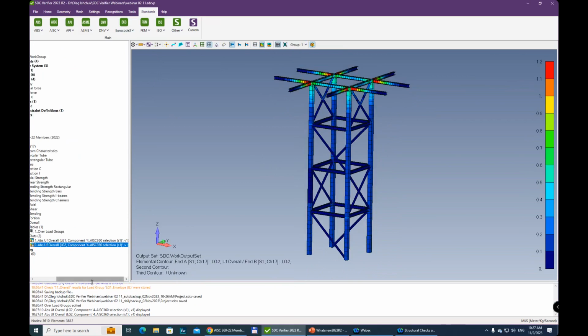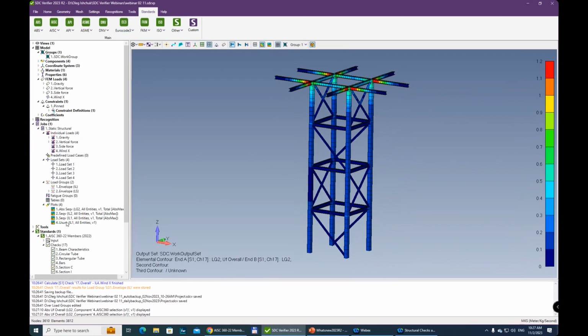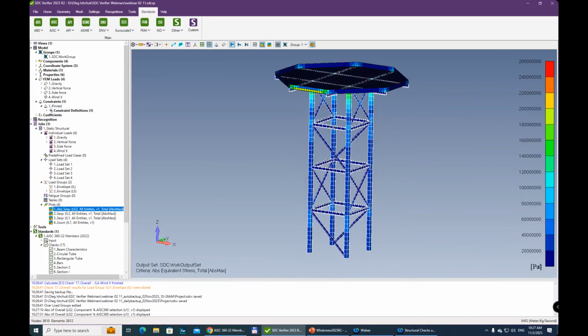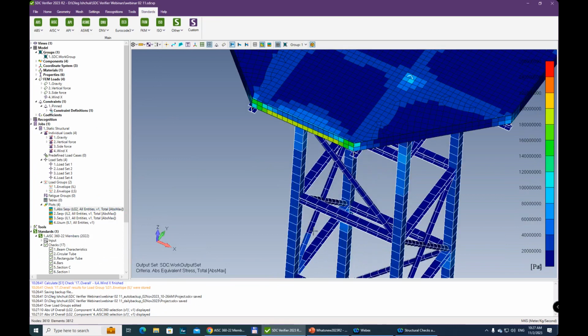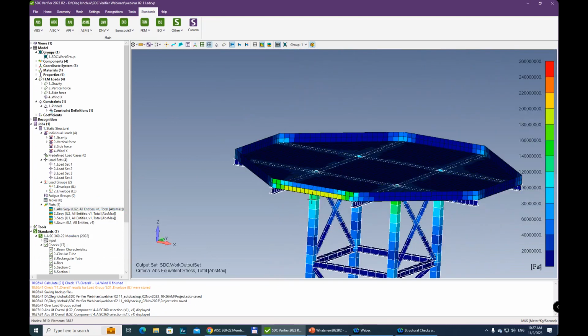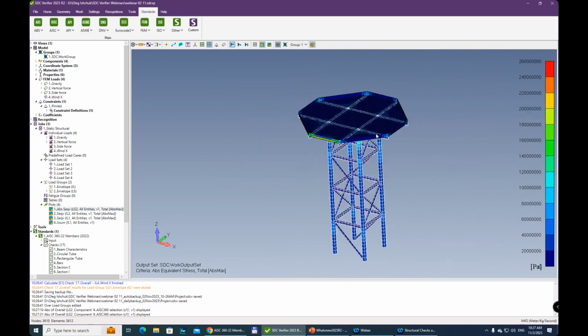Preview. That's this. I'm plotting the utilization factors, and I wanted to plot the stresses for load group. Preview. Everything is included. So back to our full model to see that we have some stresses due to side load here in this side plate. So we want to do a fatigue check.